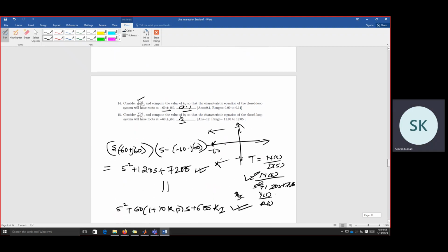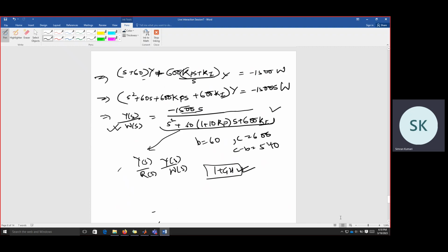So basically through these examples, we are trying to understand the concepts that have been taught in week 7. In the first few questions, we saw how these terms like proportional, derivative, and integral coefficients affect, or we can say adding these poles and zeros at the origin or the constant gain affects, the behavior of the closed loop system.